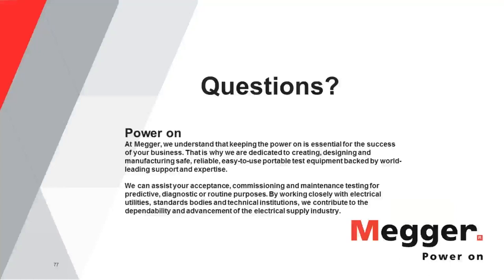So there's a point where insulation testers would not be able to help you on these activities. They might be good when you have a very bad situation on a cable and need to determine if it's a go, no go, but not for diagnostics or cable fault location. For that, definitely you need something else, and we are talking about medium voltage and up.